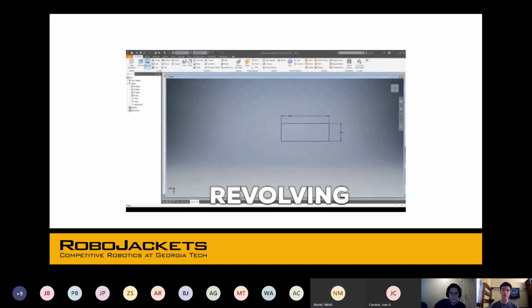Something to keep in mind is that when you click one of the sides of your shape, it will completely fill in. There won't be a hole in the center. So if you made a semicircle, a half circle, and you revolved around the middle, you'd make a sphere. And you can define if you want it to revolve 360 degrees or anything between 0 and 360.